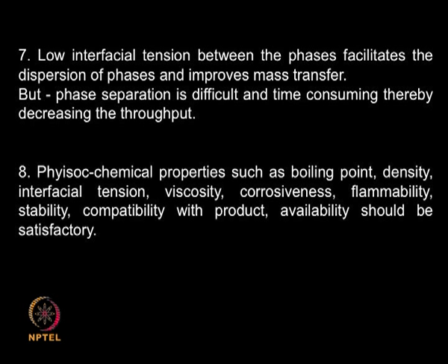The physicochemical properties of the solvent like the boiling point, density, interfacial tension, viscosity, corrosiveness of the solvent, flammability of the solvent, stability under operating condition, compatibility with the product, availability should be satisfactory. So you have a large number of requirements while selecting a solvent. For example, it should not be corrosive to the material of construction of your extractor, it should not be flammable,